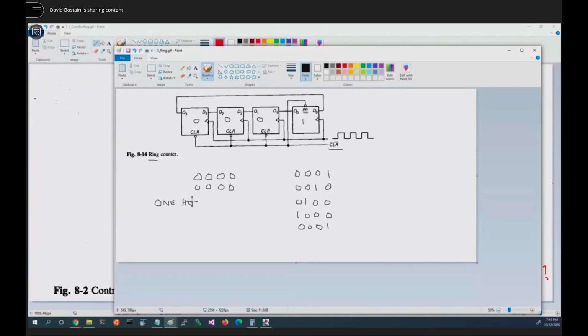Meaning, because if we were looking at our state, meaning which one is currently the hot one, there's only ever going to be 1 that's hot. Now, what would happen if we turned it on and 2 of them turned into 1s? Well, we would have problems because we'd pass those 2 1s around that ring over and over again. It's called a ring because we go around a ring with the signal. But if we had multiple 1s, that would be a problem.